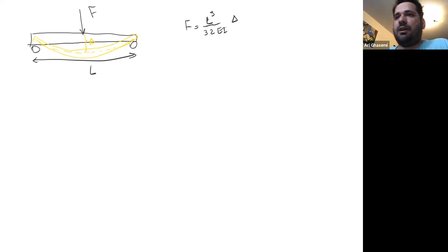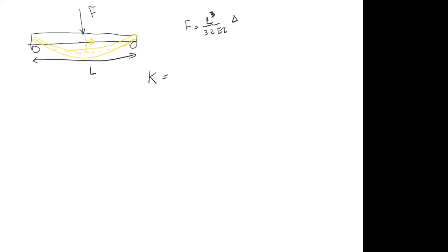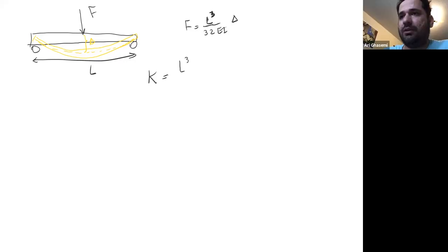Now, if I just ask you to find the spring constant, what do you write? What is the spring constant here? L cubed over 32 EI? Exactly. 32 EI over L cubed. You see, it's independent of force and deflection.